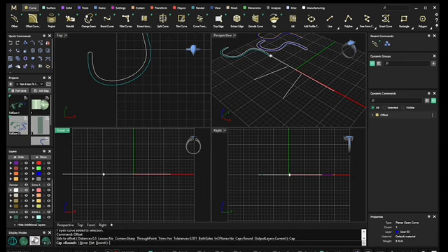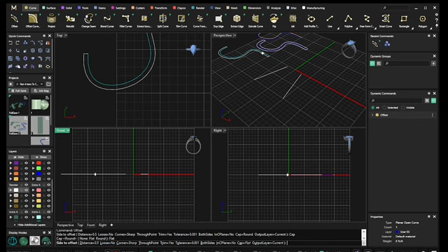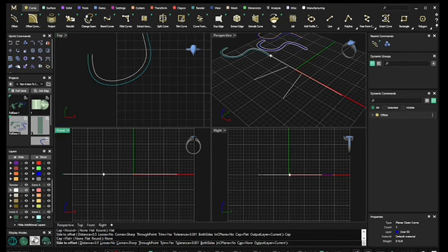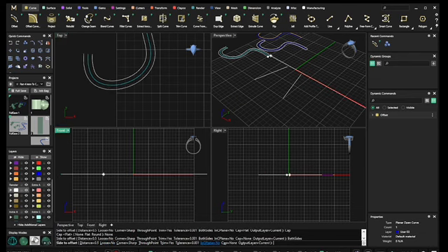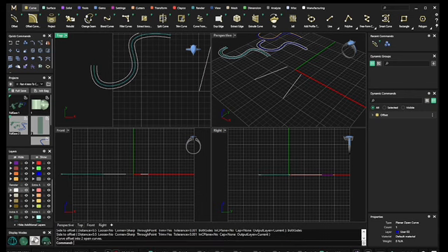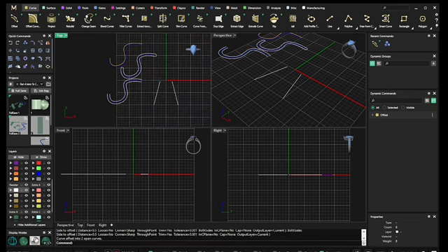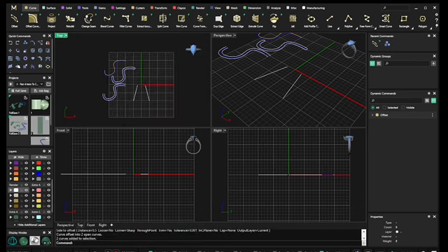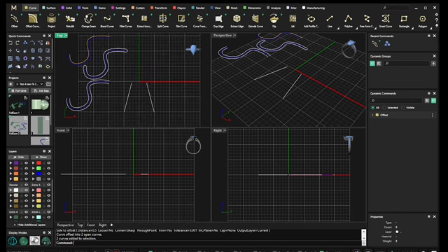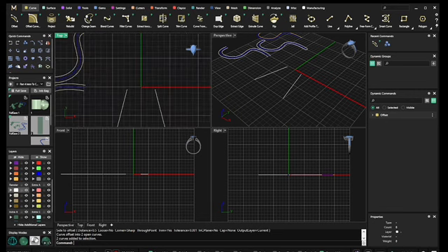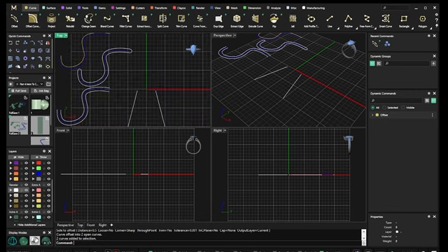So if I change that cap to a flat cap, or if I change that to none, it automatically only offsets on one side. So if you want both sides, you have to punch that in. And there you go. It's very easy. So we will have to see about this. As I go along, I'm going to learn more and more about the dynamic commands and the parametric design.